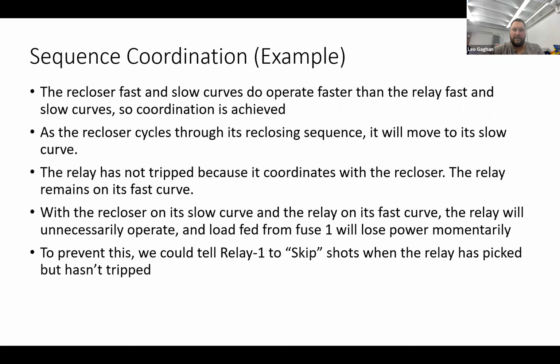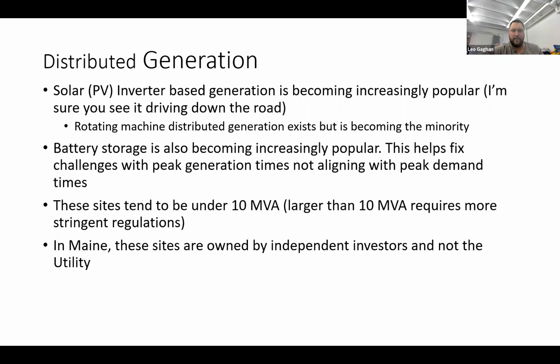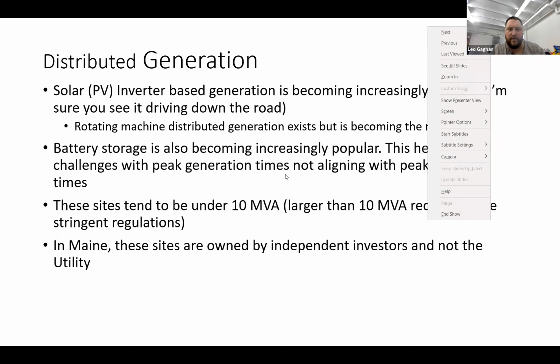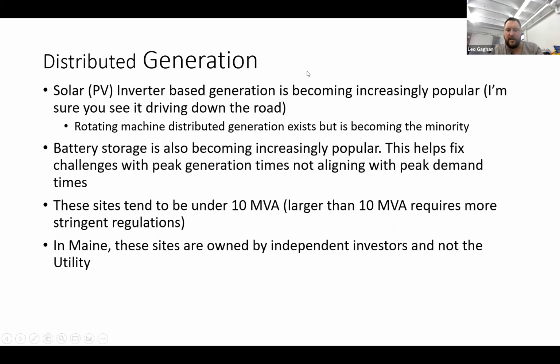That's the basis behind the sequence coordination, is making sure that our relay will skip shots whenever our downstream recloser trips and we pick up, so that we can stay in line with the recloser as it goes through its reclosing sequence. So that was sequence coordination.